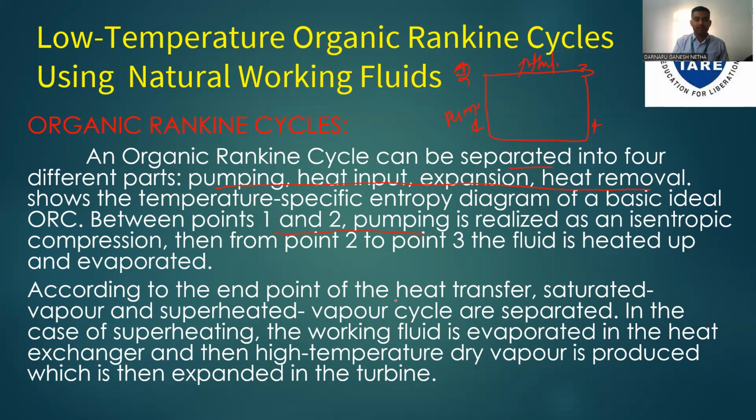According to the endpoint of the heat transfer, saturated vapor and superheated vapor cycles are separated. In the case of superheating, the working fluid is evaporated in the heat exchanger, then dry vapor is produced, which is expanded in the turbine.